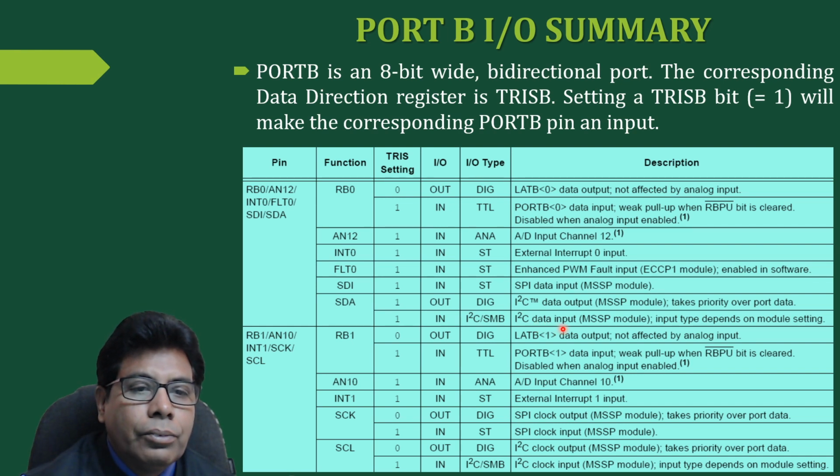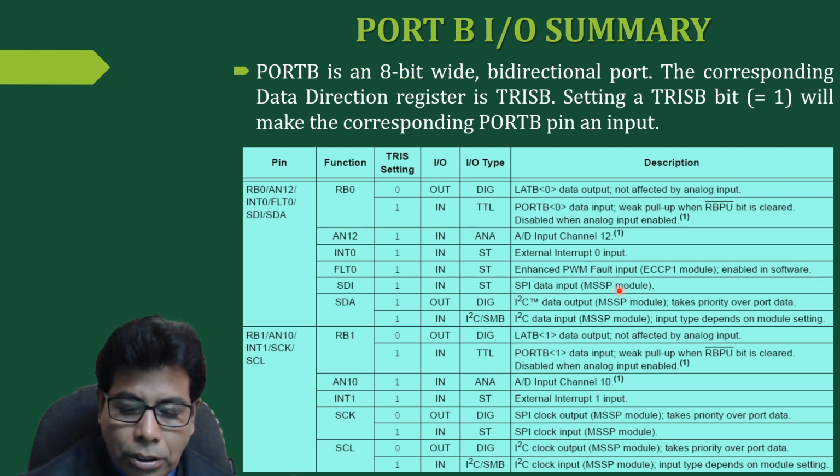Then the second pin which we are going to use is the SCL. So when we configure it by using the TRIS bit 1, then we'll get this functionality, that is I2C clock input in MSSP mode. So we'll be using the SCL and SDA, these two pins for the I2C mode of the MSSP.